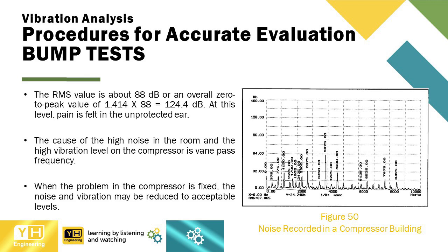The cause of the high noise in the room and the high vibration level on the compressor is vane pass frequency. When the problem in the compressor is fixed, the noise and vibration may be reduced to acceptable levels.